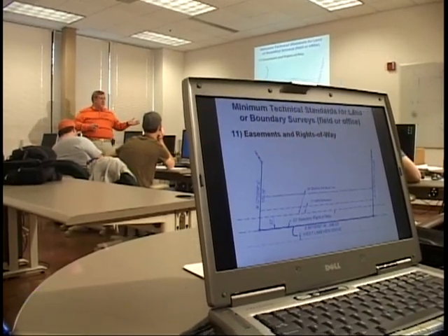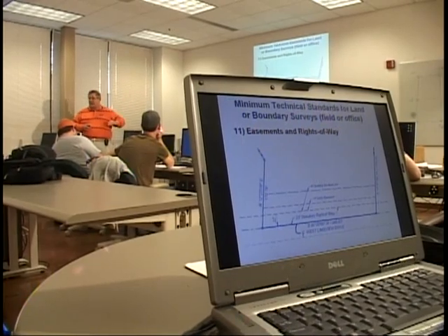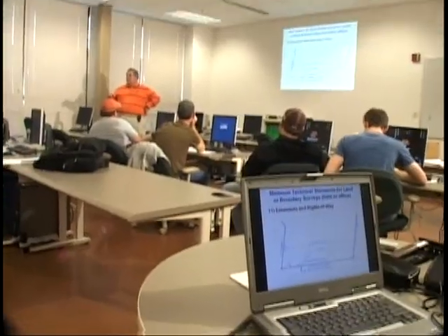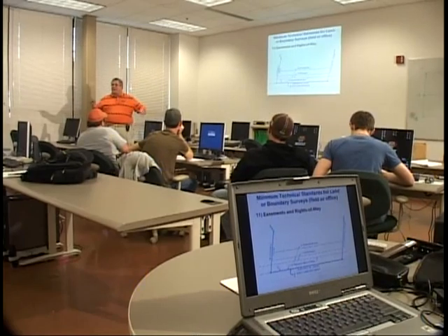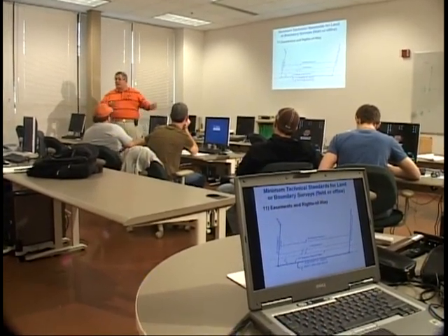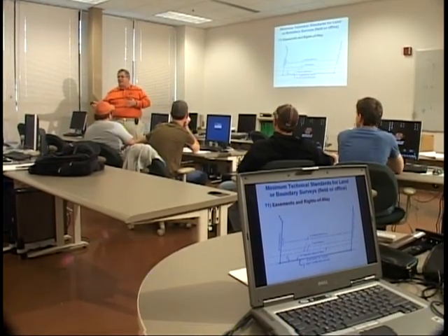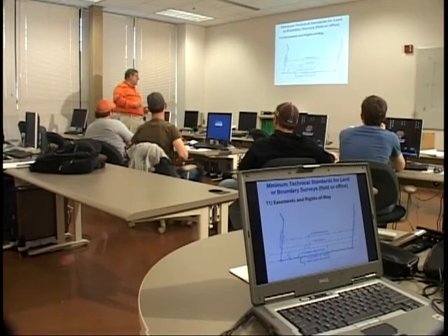In the majority of Tulsa County, the right-of-way granted on each section line on each side is a 2-rod dedication. How do you find out what that information is? Well, you can go to the Oklahoma Society of Land Surveyors website, and you can download a map that shows you county by county what those right-of-way dedications are.